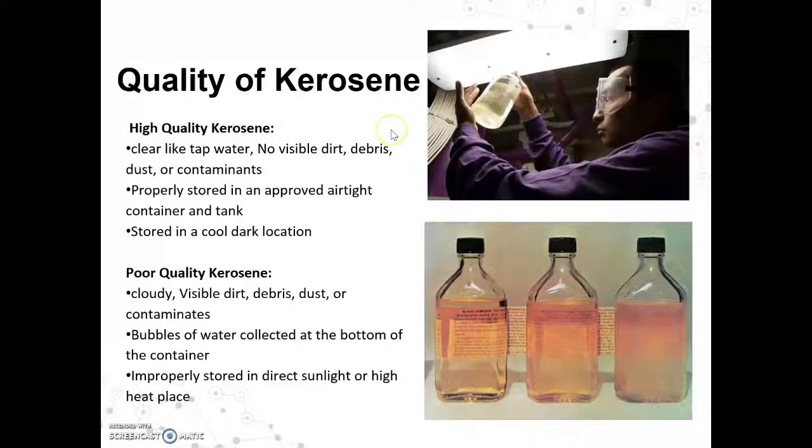There's high quality kerosene. It looks like this bottle. It's clear. You can see through that. And good high quality kerosene is always properly stored in an airtight container or tank, also stored in a cold, dark location. And the second bottle has some water or sediment in there. It's okay.